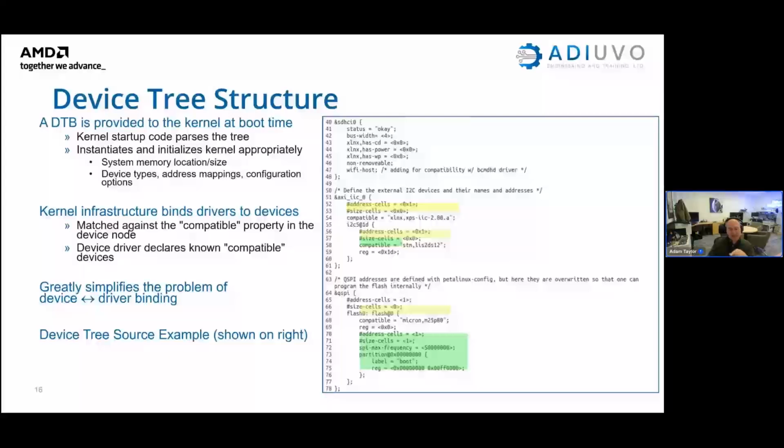So for Cylin, this is actually generated by PetaLinux as we go through it. But this little bit of a file where we add in this little bit of information, we have to do by hand, but AMD have a lot of guidance and show you how to work with it. If you think about it, it's a very simple thing. If we put hardware in the programmable logic, then Vivado knows about it, and it can be put in the XSA and pulled through into PetaLinux, and PetaLinux knows about it, so it knows what drivers to pull through and to mount.